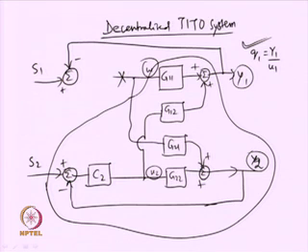You need to redraw this a little bit to find the ratio between y1 and u1 and subsequently Q1. So, to find that, in the reduced or modified block diagram, G11 will get connected; no signal is coming there, rather your G12 is coming over here, because this signal is the same as U1.